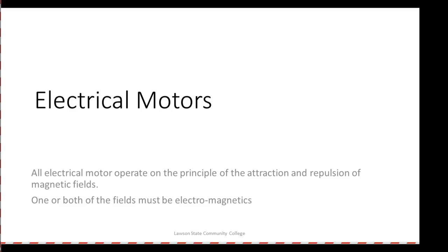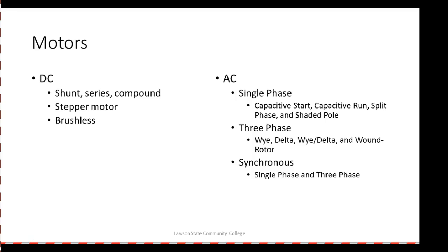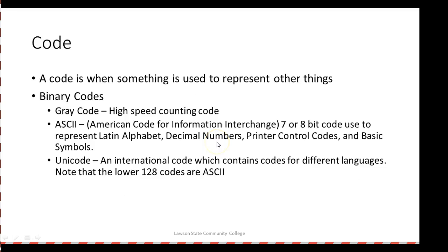It'll run forever. A rotary actuator might go more than 360 degrees, but eventually it's going to hit an end stop and it's going to do what? Stop. So a rotary actuator, the stroke is limited mechanically, right? You understand that, by whatever we're running it with. An electric motor has an unlimited stroke.